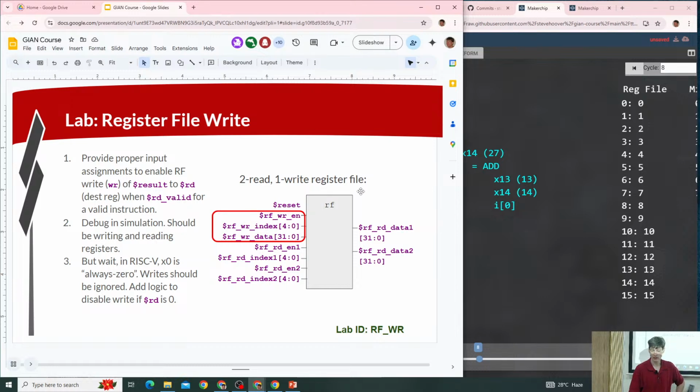So again, when we instantiated that macro for the register file, that gave us these 3 dangling inputs, which we need to assign. So create the assignment statements for these 3. The macro is instantiating the logic of the register file.